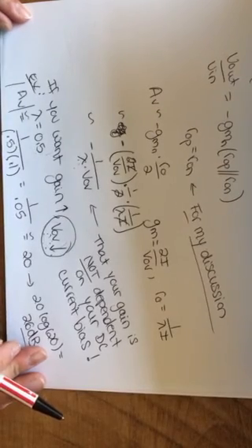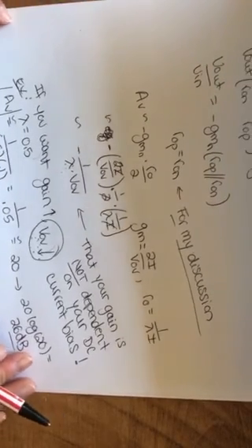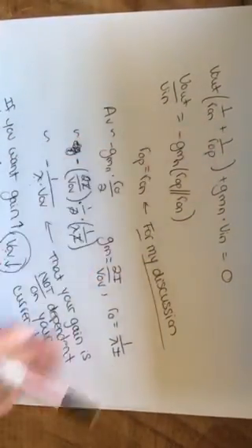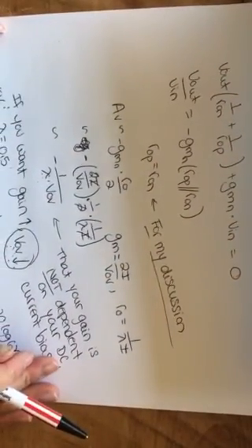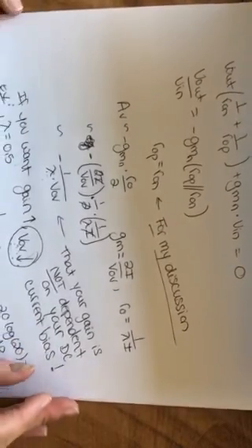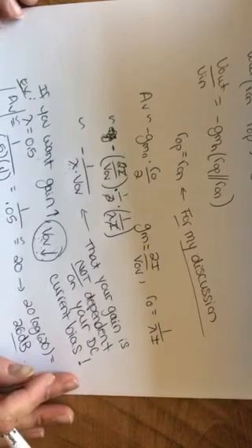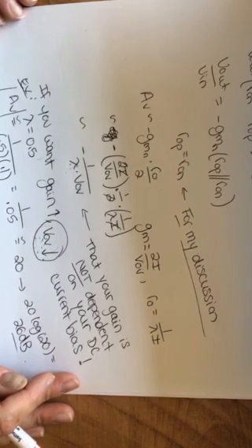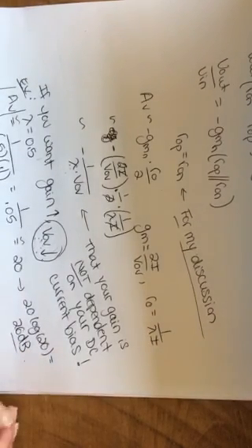Okay, and so remember in Lab 4 part 1, when you are finding the lambda of your device or the early voltage, the motivation for doing this in the end is to find your output resistances, because your output resistances are dependent on channel length modulation. Okay, so please keep that in mind. That is why you are doing part 1 of that lab, plotting those IV curves and finding from those IV curves early voltage, lambda, and hence output resistance r0. Good luck.